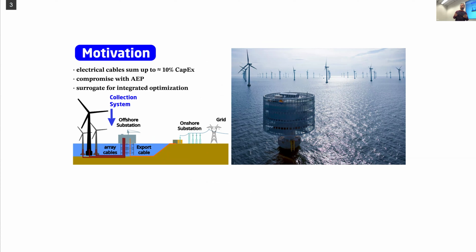When you are optimizing for energy production, which is a major factor in the economic accounting of a project, you look to reduce the effects of one turbine on other turbines, where you have the wake of the turbine that's generating power. It will reduce the wind speed and generate turbulence. So you want to spread them as far apart as possible to get more energy production and less loads on the blades. But this will increase the cable costs.